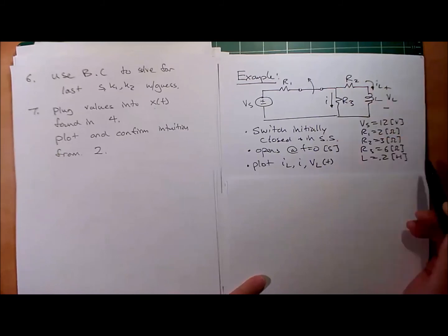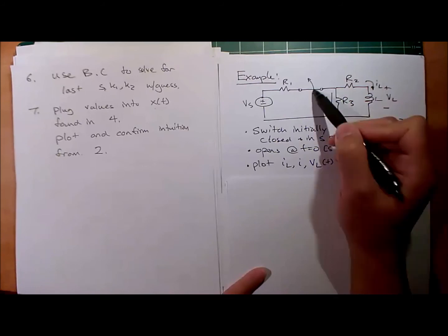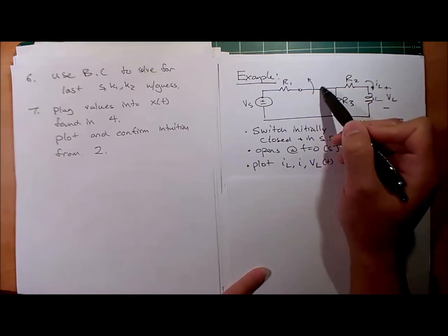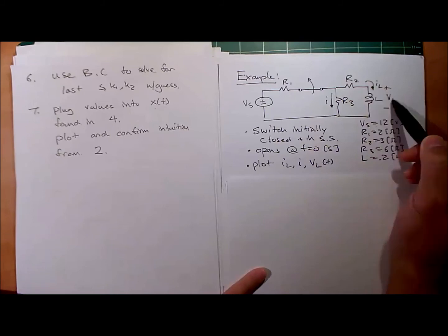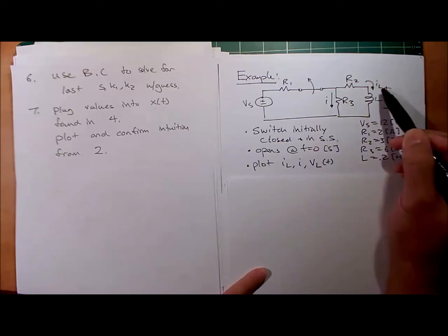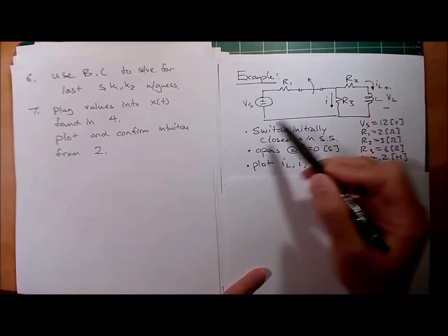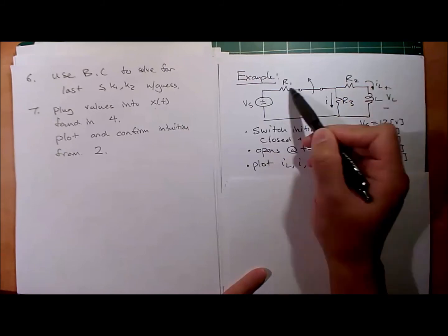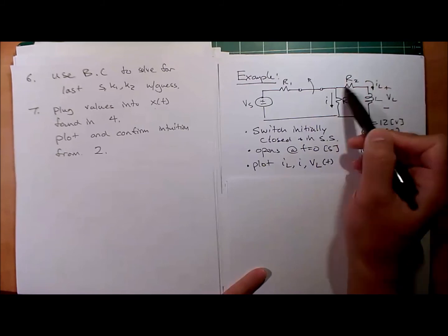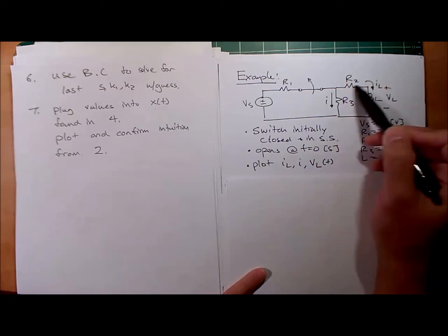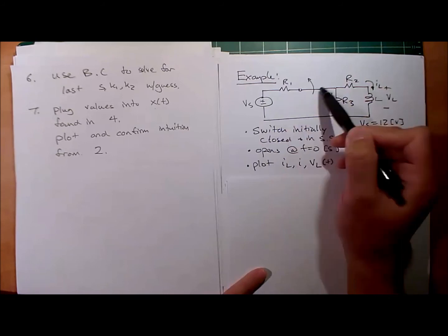Okay, so when this is closed, we'll say it's steady state. When this is in steady state, the inductor behaves like a short. So it's like a wire. So the voltage is going to be 0. These two currents are not going to be 0. You can imagine current's going to leave this and flow into both via a current divider kind of situation. So you're getting non-zero steady state current when this switch is closed.